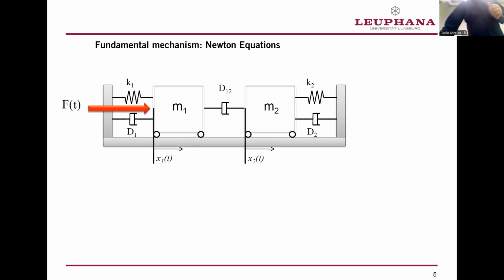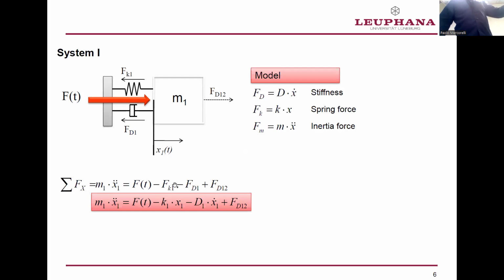We can understand that the spring works against this, the damping element of the friction works against, but also this one. Why that? Because if you fix M2, it's clear that it works against. Just to express, then we will see if this is moving how it changes, but always against. And not only, also the inertia works against. I mean, a big mass is more difficult to move, or to be moved. No wonder this minus here.